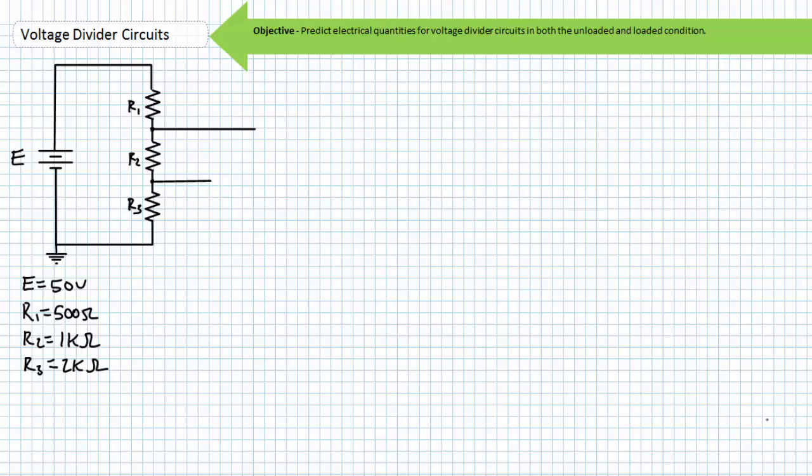If nothing is connected to these nodes, or the switches between the nodes and the electrical loads are open, this is an unloaded voltage divider and can be analyzed using the simplest of series circuit techniques because there is but one path for current to flow. An unloaded voltage divider, as the name implies, is a perfect opportunity to apply the voltage divider rule.